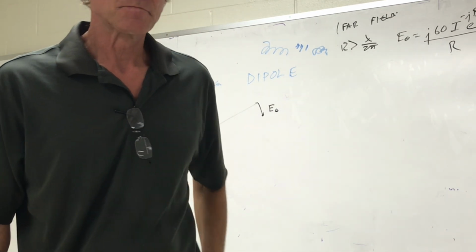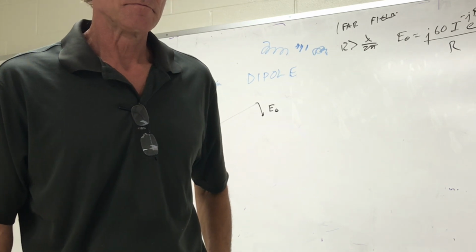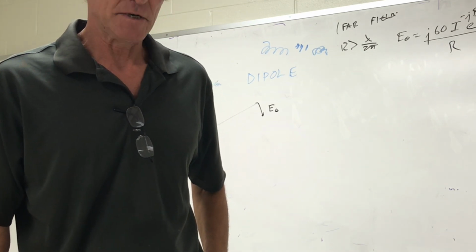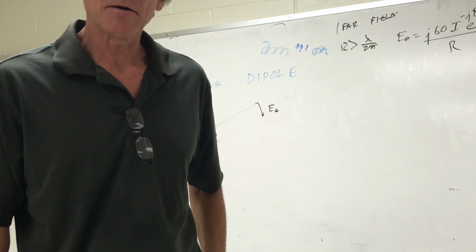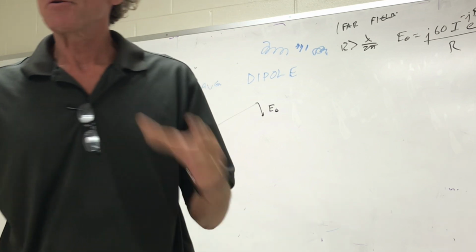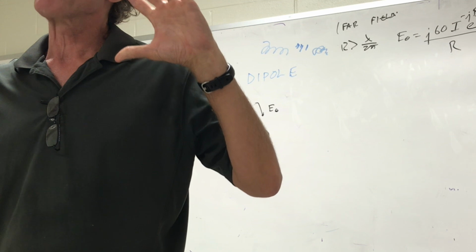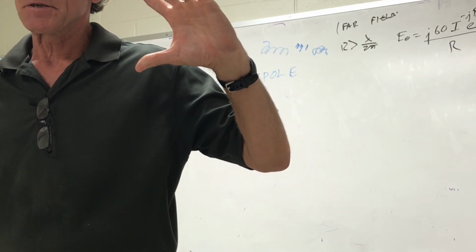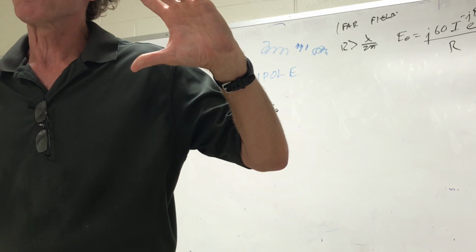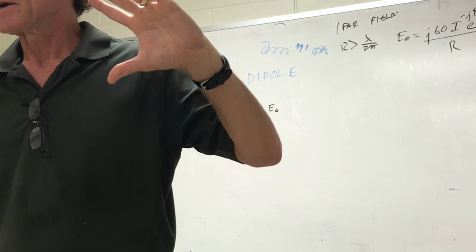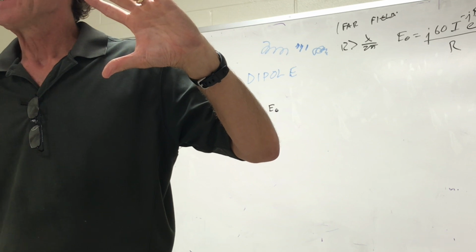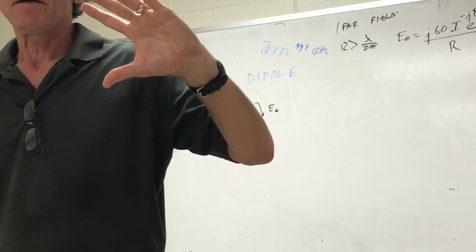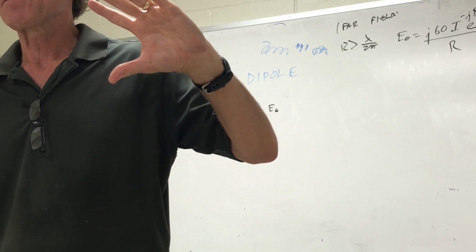Go ahead. But if F goes up, isn't D going down? D is a measurement in meters. No, listen, if you have a dish antenna, it doesn't matter how high a frequency, the only thing the frequency does is focus it more. And this is beyond us right now, but the higher the frequency, when you have an aperture antenna, the further away you have to be for the far field.